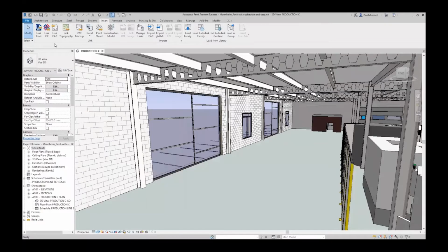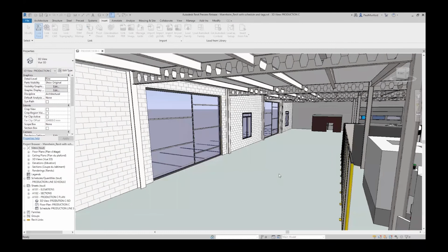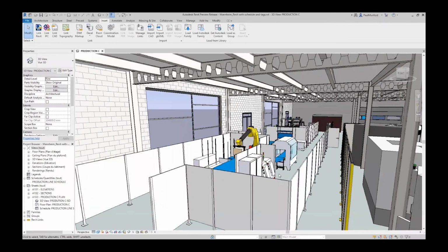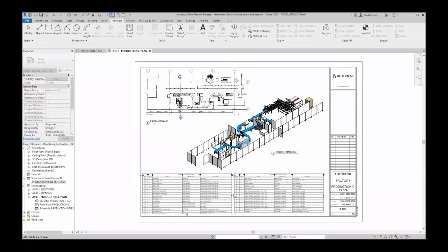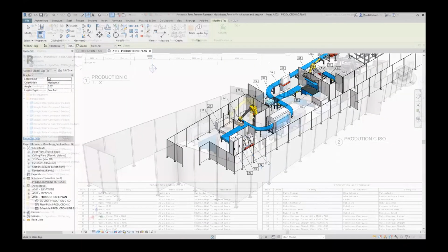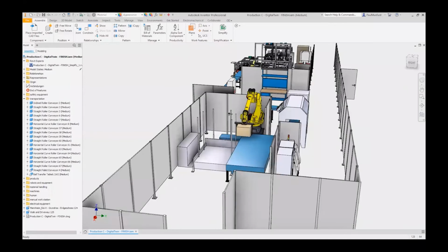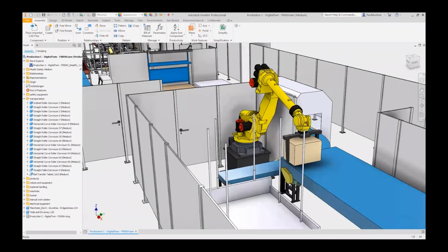So the new Simplify dialog also includes presets, which help to further automate your simplification process by saving standard settings so that you can use them again and again when you need to export to Revit. When we're happy with that, our simplified model shows the appropriate detail. We can click OK and export that to a Revit project.